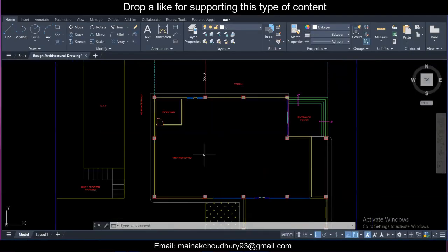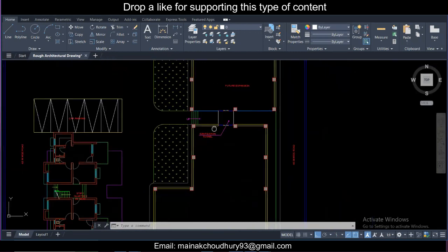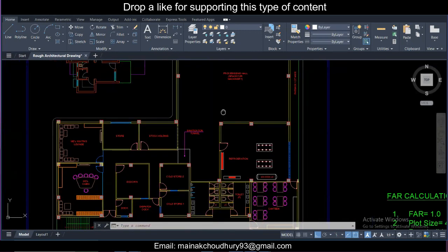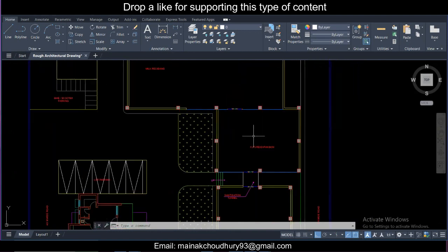So as you know, the first step for the design process is the marking of the columns. So this is the plan we have received from the architect, and he has already marked the columns here. Initially, as a structural engineer, you should check whether these columns are sufficient or not. And if these are sufficient, then it's okay. If not, then you can suggest additional columns.